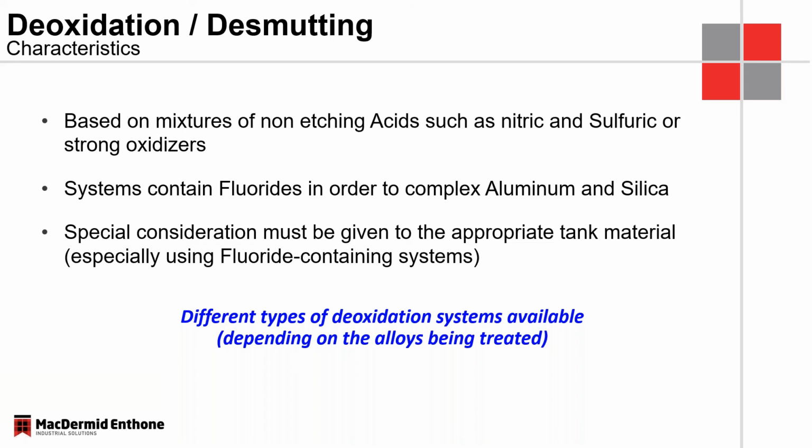And what we always say, we have to understand that formulation. If we do have fluorides, we have to pay some attention to tank material and the surrounding of the deoxidation tank. Again, there's a deox for every application. There's a specific deox for more complicated alloys, higher alloyed aluminum substrates.